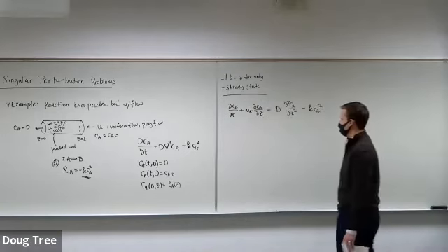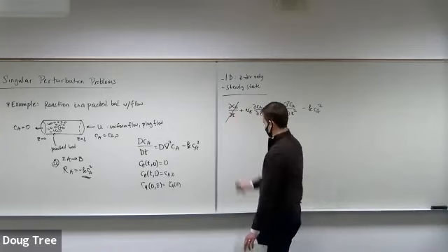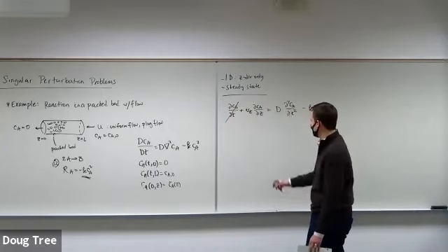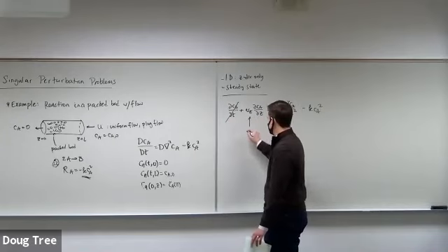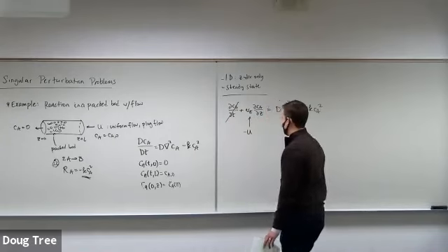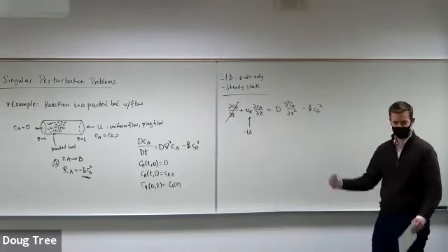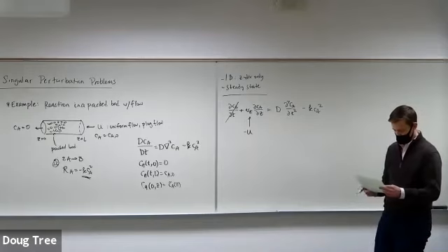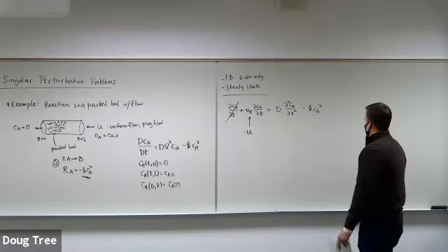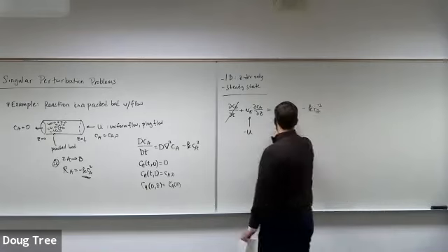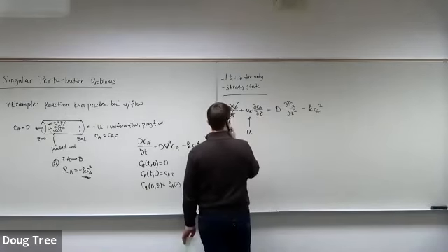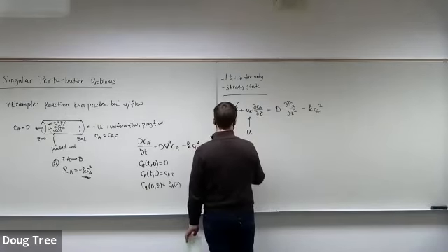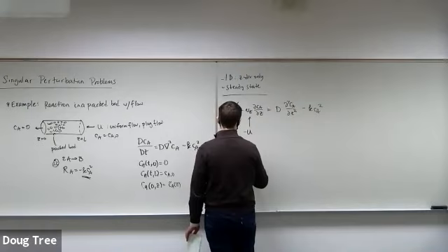And then I can do this guy, and I get steady state. And I know what v_z is. That's minus U, right? U's flowing back that way. And I'll rearrange. I'll put this guy up front, and everything becomes a total derivative because now I'm down to only z derivatives. So I have D for the diffusivity, d squared C_A/dz squared.